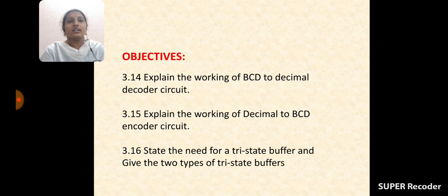So here the naming of 2x4 and 3x8 also comes from the mathematical expression of 2 to the power of n is equal to the number of outputs. So here 2 to the power of n is equal to 4 means the decoder has 4 output lines, n is equal to the number of inputs. So 2 to the power of 3 is equal to 8 means 3 input lines are there, 8 output lines are there. So these are the different combinational logic circuits.